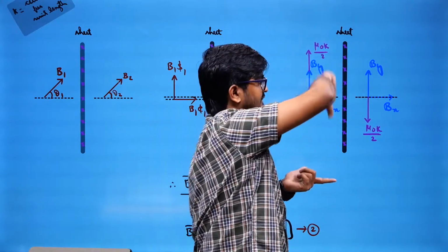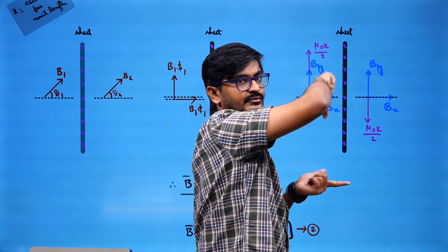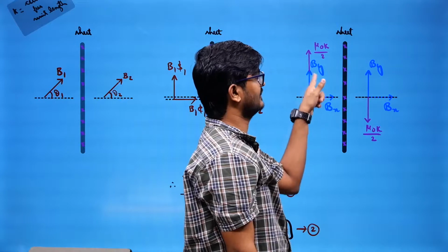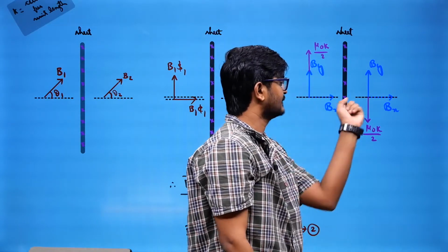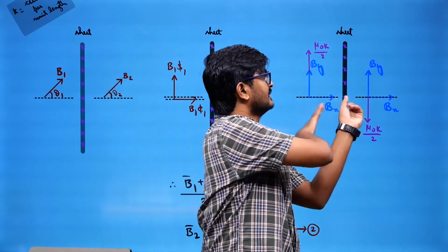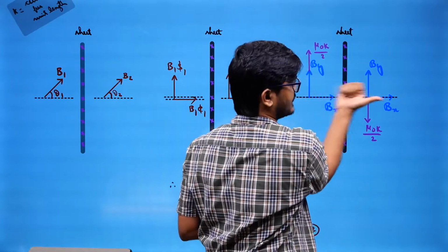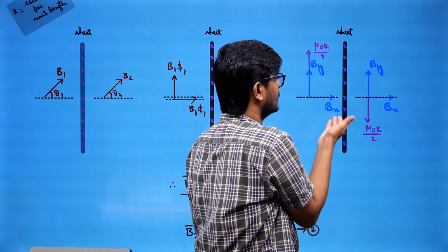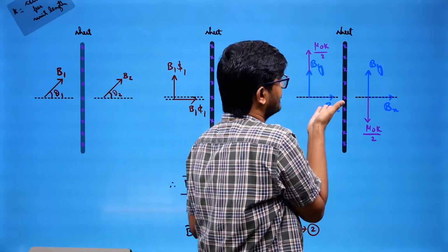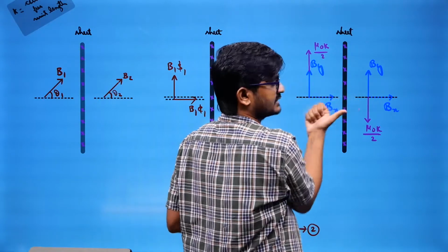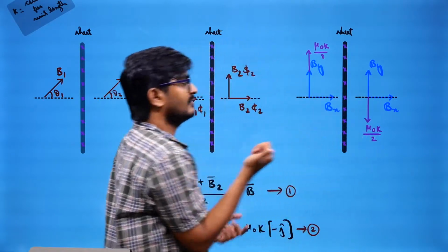But this force is not required for me because it is not going to give pressure. If I want to find the pressure force, that must be because of this magnetic field. That is, if the current carrying wire is in the magnetic field this way, then it is L bar cross B bar. So that is the force which is needed for me. If I take some current carrying element and find the force because of this By, that is going to give me the force in this direction. If I divide by area, then I will be getting pressure.